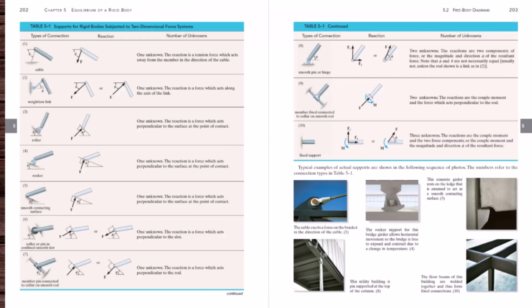And so we talked about how to analyze what forces to put in whenever we remove a connection and have to add forces corresponding to that connection. We talked about how to rationalize this. You think about what motion this connection is preventing the body from doing. If it was preventing motion, then you put a reaction force in that direction. If it wasn't preventing motion, you don't. And typically reaction forces are unknowns, but they don't have to be. Maybe I know that the force in this pin is going to be this force, so what is the external force going to be to correspond to that? You could look at it that way.